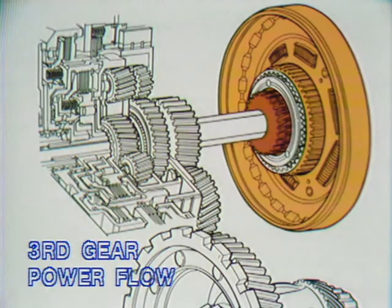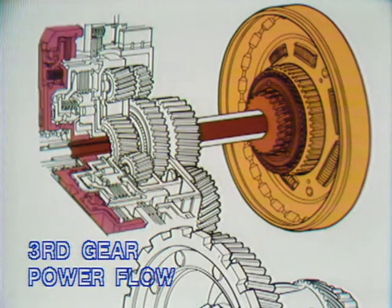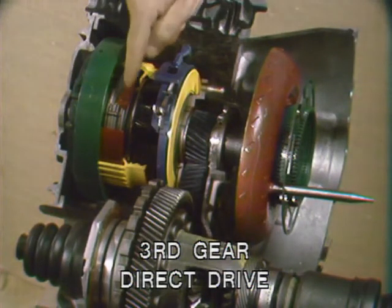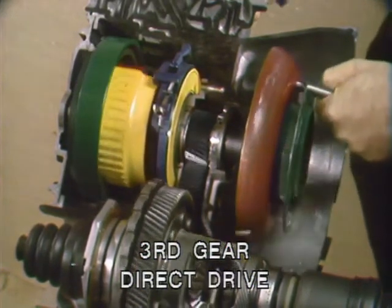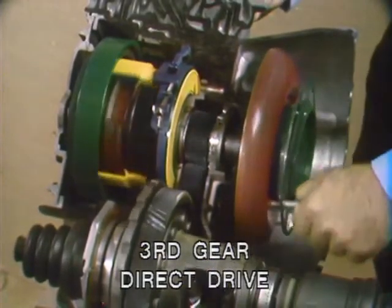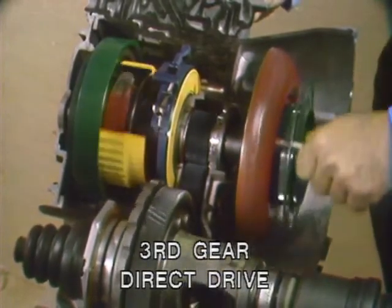High gear power flow is from the converter turbine and cover to the splitter planetary unit, then to the intermediate shaft, intermediate clutch, ring gear, main planetary unit, and final drive. Watch as Joe demonstrates. He has locked up the direct clutch and the intermediate clutch and is turning the intermediate shaft with the turbine. This simulates a coupling condition in the torque converter, which is what causes the main gear train to lock up. One turn of the input shaft equals one turn of the final drive input. The gear train is locked up in high gear.